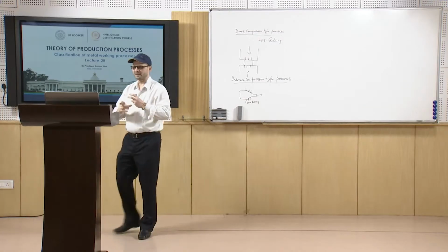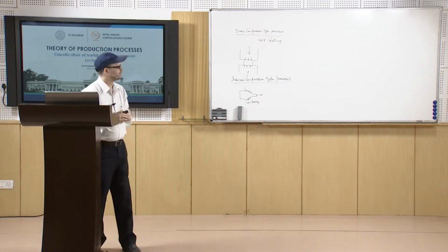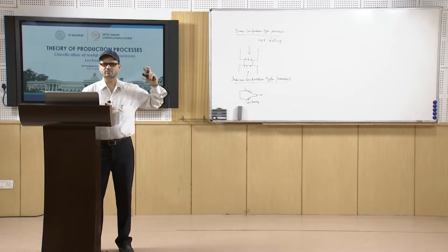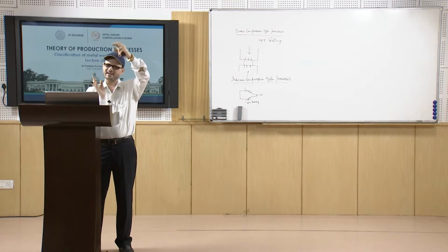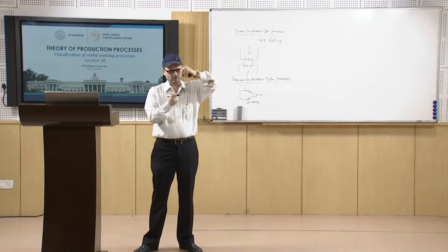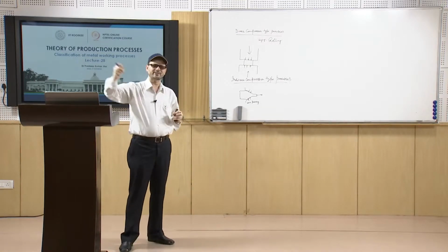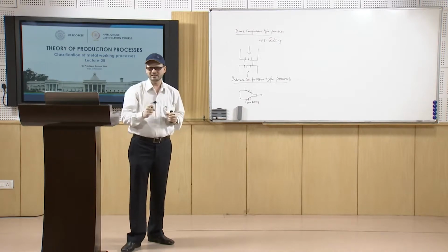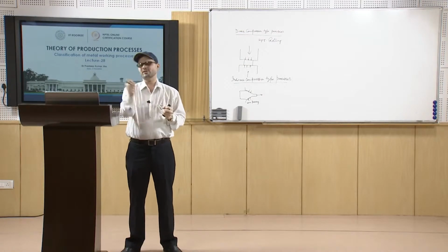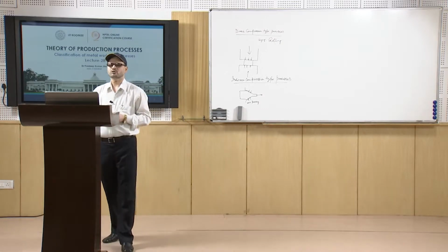Similarly, you must have seen the process of extrusion. In extrusion, you apply the force and the material goes out, but there are compressive stresses developed on the sides. Because of that compressive state of stress, as well as the applied force, tensile stresses are developed at the exit. Because of these combined or complex states of stress, the material flows through the die opening. That is known as extrusion.